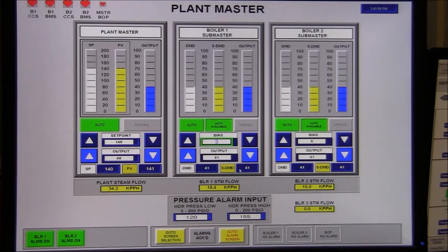Boiler 1, for the same firing rate, will put out a little bit more than boiler 2. I've been told that there's some restriction in the gas passes on boiler 2. That reduces the total airflow available to burn the fuel, and so end of discussion is that the boiler 1 output for a given firing rate will be a little bit higher than boiler 2.